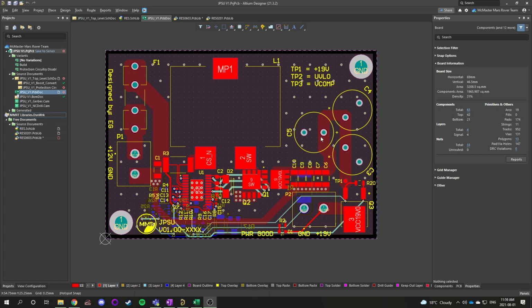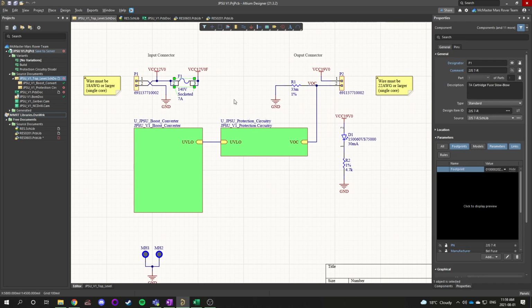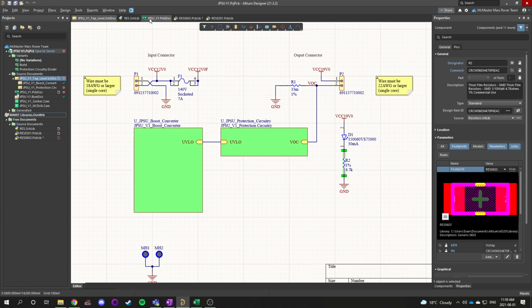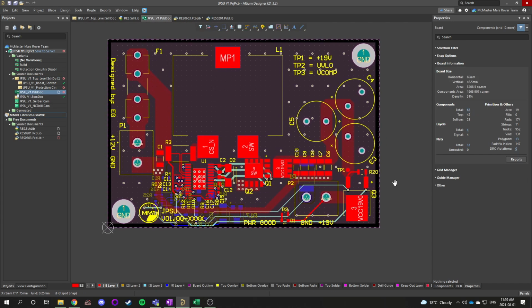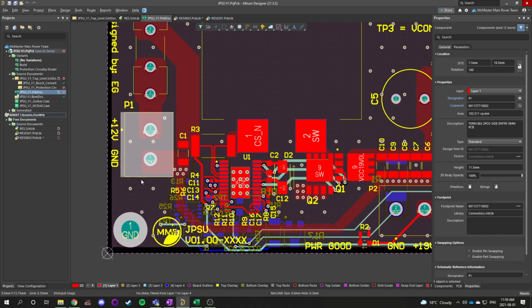Okay, so your printed circuit board is basically the physical representation of your schematic in the real world. In a similar vein to how the schematic is composed of schematic symbols, where all your components are represented by schematic symbols like this connector and this fuse and this resistor, components are represented on the PCB by using PCB footprints, or the footprint that the component takes up on the board. So this would be the footprint for that 2-pin connector.